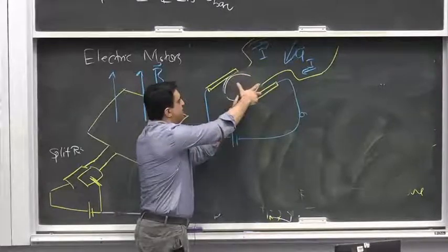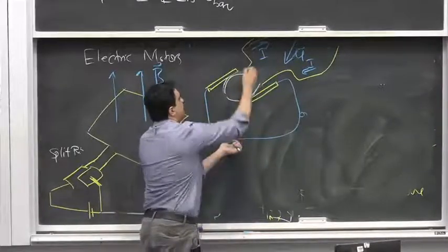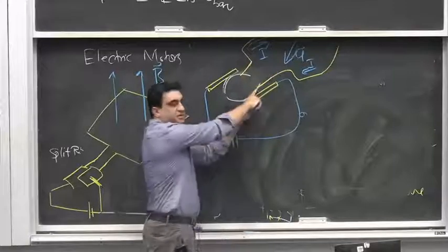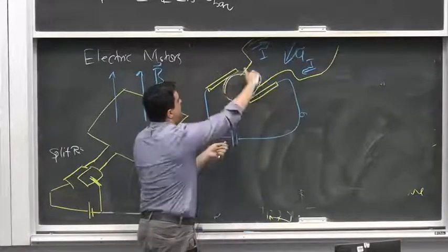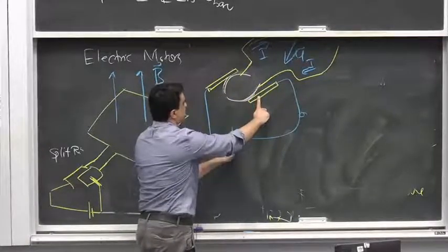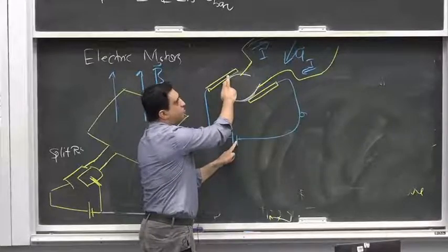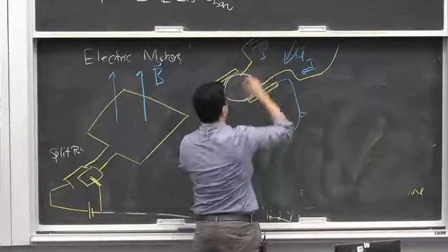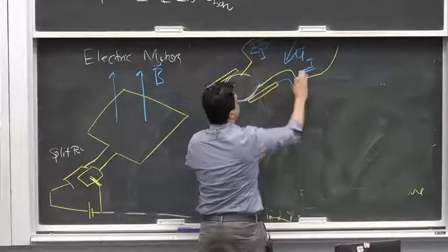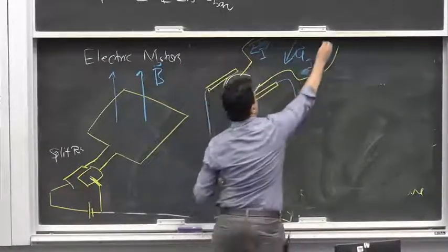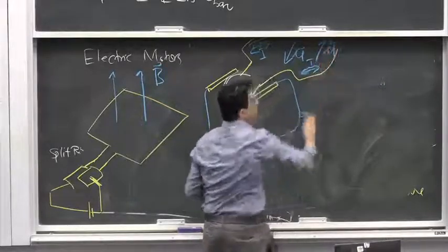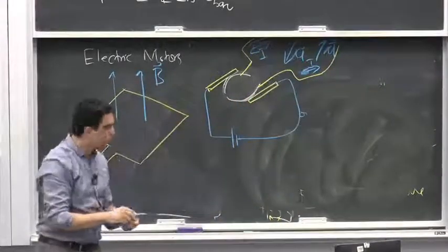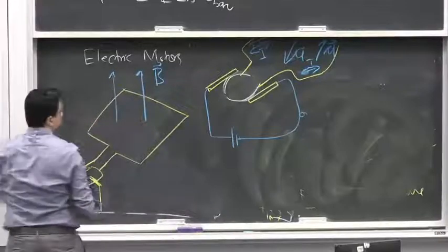So when this thing rotates, what happens? These connections do not change, these connections stay, but the brushes change, so this one will now connect with positive, negative, and this one will then be connected with positive. When it is reversed, you would have a current flowing in the opposite direction. So you would have a magnetic moment now in that direction. So what does it mean here?